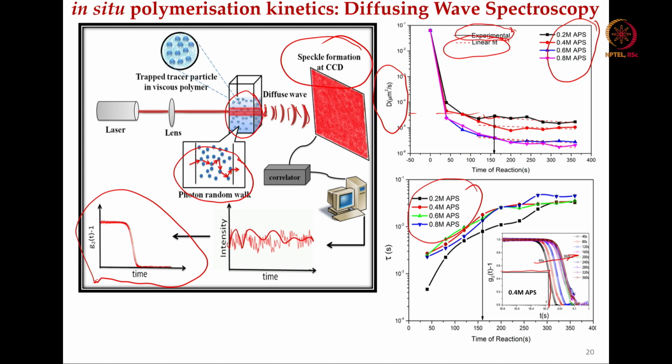So, I repeat, these are physics based measurements which were used to quantitatively analyze the polymerization kinetics happening at the binder jet powder interaction front. Okay. So, the two things that we have found out from here are the D value, that is the diffusivity constant, and how it varies with the time of reactions, and remember the time of reactions is always in seconds, and the relaxation time, which is the characteristic time constant that we have used in this particular time of reactions.